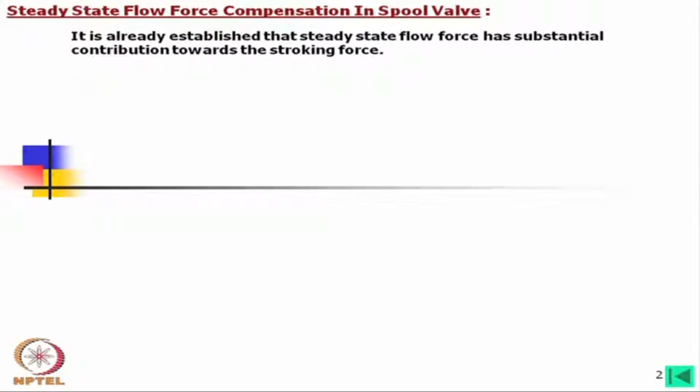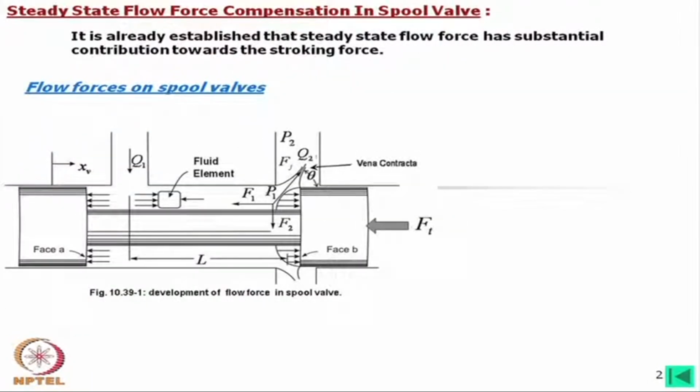Now, it is already established that steady state flow force has substantial contribution towards the stroking force. If we look into this figure, which you have seen in earlier lecture, that how the flow force is working on the spool.